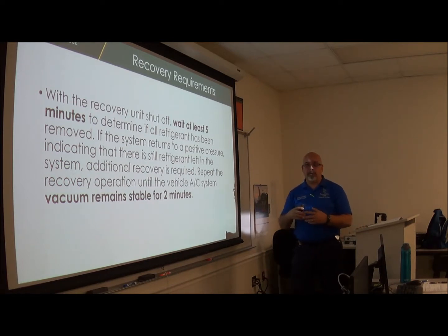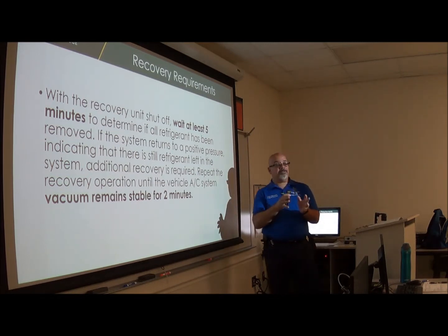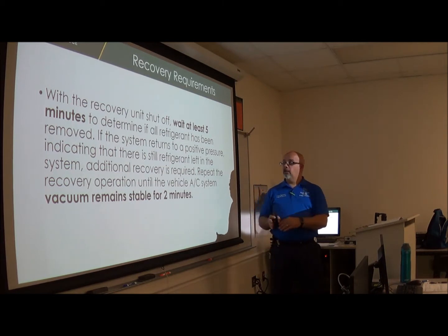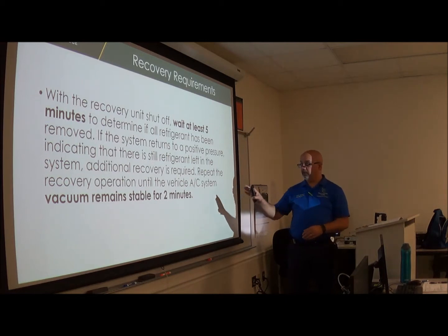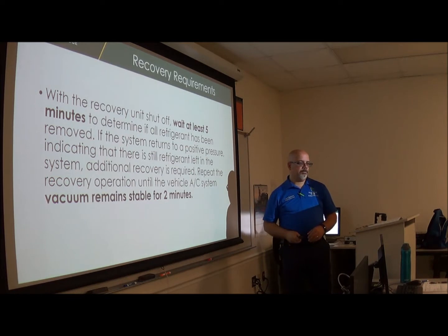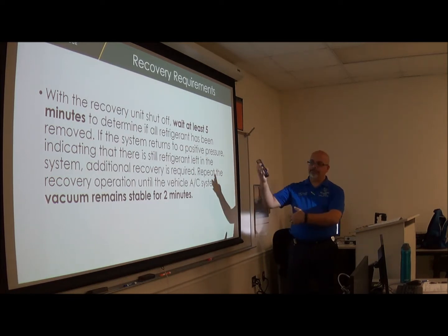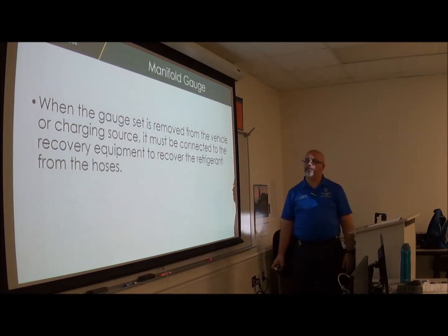So if we were doing a recovery that lasted maybe 10 minutes, and then we waited the 5 minutes and it went back to the positive side, that means that there is still refrigerant in there. Okay. So we're going to have to give it more time for recovery. Then we will repeat the recovery operation until the vehicle AC system vacuum remains stable for 2 minutes. Okay? So that's kind of a double check to verify that everything is good.